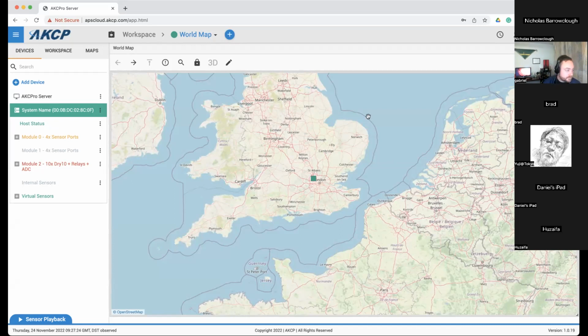So as Gabriel showed, when you are setting up the CFD simulation, he input some arbitrary numbers. So the temperature of the air coming out of the crack, the return air temperature, and the power of the racks. And that's how typical CFD works. You input these basic values and they give you a simulation as a picture of what your data center should be like. In the real world, though, it's not like that. And that's why we call this sensorCFD, because we're using the sensor data in order to constrain that CFD model.